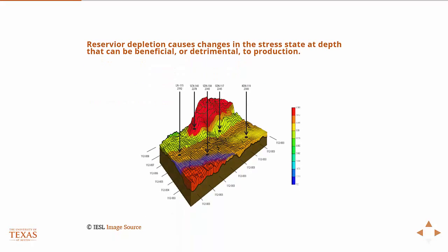Another way that stress is important is in the reservoir depletion. So as we drain a reservoir, and this is sort of the other aspect of stress, is the actual pore pressure. So most rocks, certainly the ones we care about, are saturated with oil, natural gas, condensate, water, other things, right? And as we drain that fluid out, we're basically depleting the pore pressure as well, which sort of affects the overall stress in the material. And that can be a good thing, and it can be a bad thing.